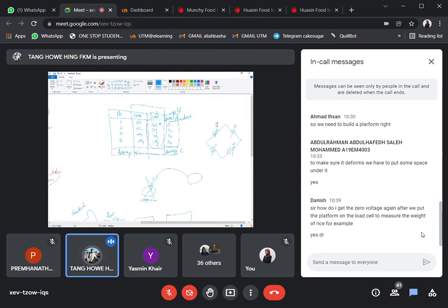We have 4 load cells, and therefore, if let's say one of the load cells is malfunctioning or doesn't have the identical resistance, then most probably you are not going to be able to change it. All right. So in that case, I don't think you will be able to zero the offset voltage using this Wheatstone bridge, because you cannot change the load cell.